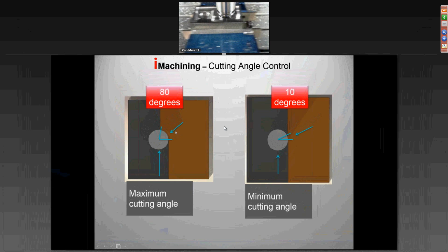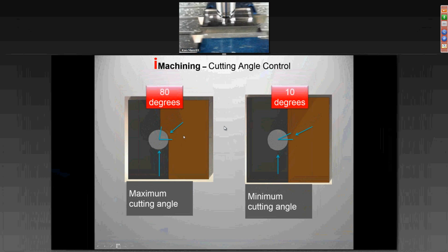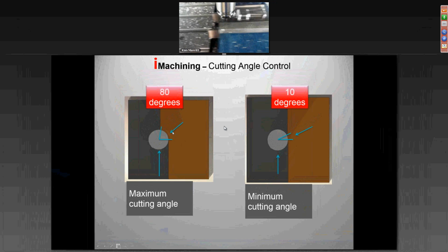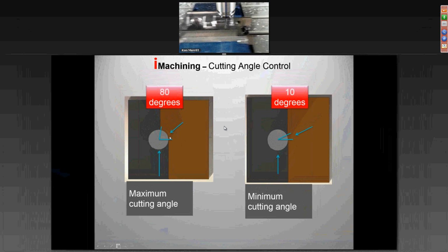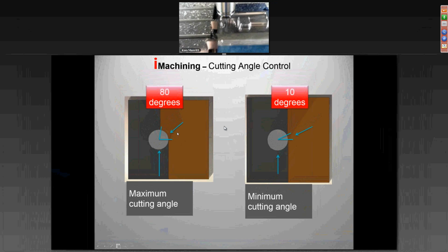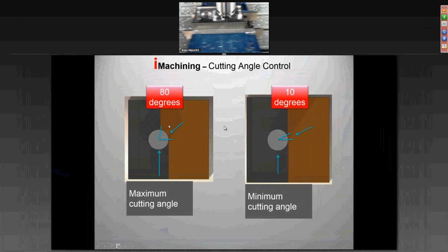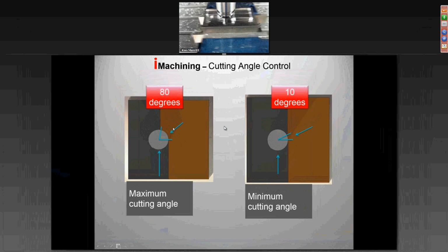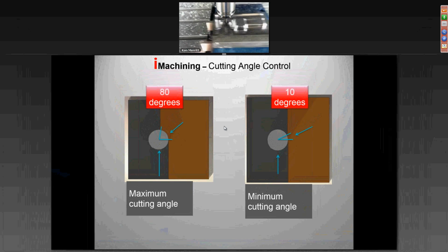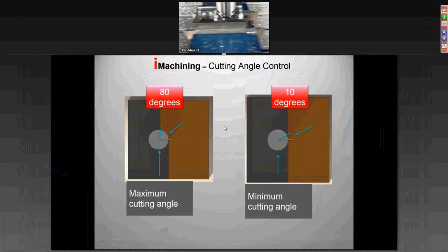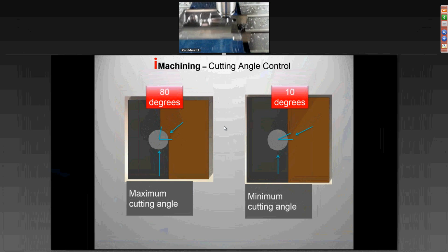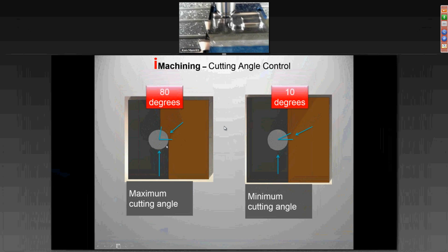Below 80, we don't really notice any of that. And so we looked at the efficiency of the tool path between 80 and 85 degrees and realized that it's pretty negligible, so it didn't make any sense to push it up to that limit. We went ahead and kept it down below 80. Most of the time that I'm cutting, I'm running 65 or below. 60 is where I like to run things in soft steel. If I get into some really hard steels, I'll roll it down to 35, 40 degrees if necessary. But that's why the maximum angle is set where it is.